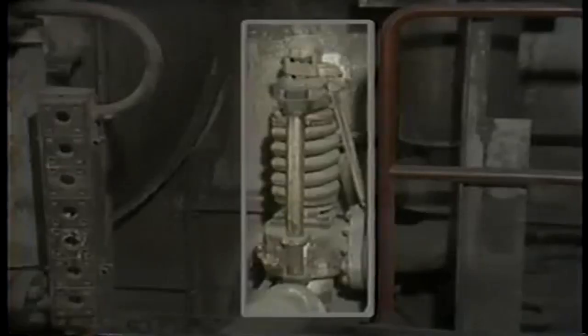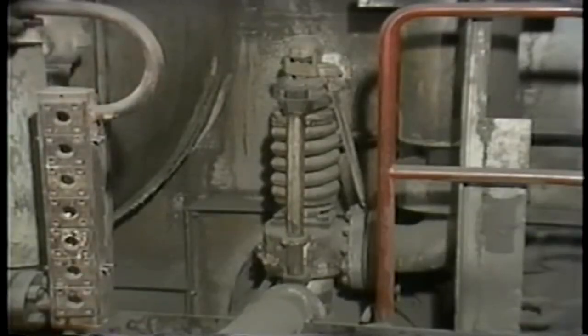If steam flow is stopped, the turbine generator can't operate. Also, unless an alternative flow path for the steam is provided, pressure and temperature inside the superheater and reheater tubes will increase, causing them to overheat, rupture, or even melt. To protect superheater and reheater tubes from overpressure and to provide an alternative flow path for steam, safety valves are installed in outlet lines of superheaters and reheaters. If steam flow to the turbine generator is cut off, the resulting increase in pressure will cause the safety valve to lift. This, in turn, will provide a flow path for steam, protecting the tubes from overheating.